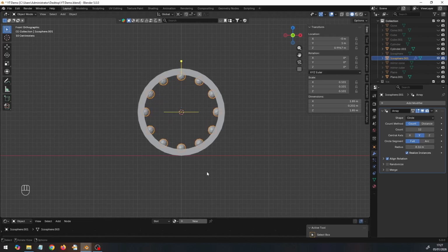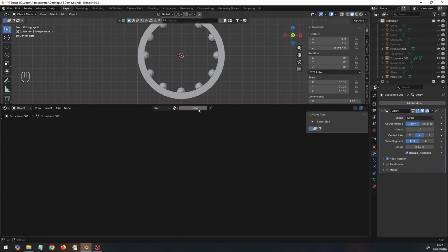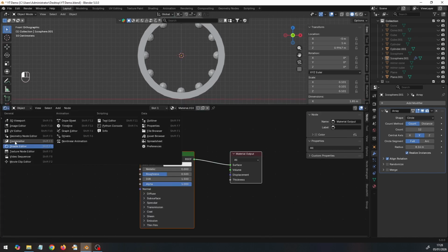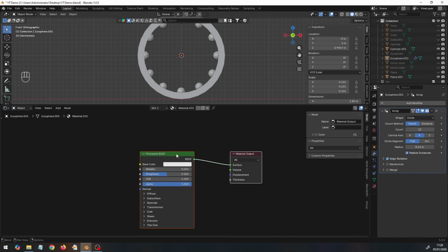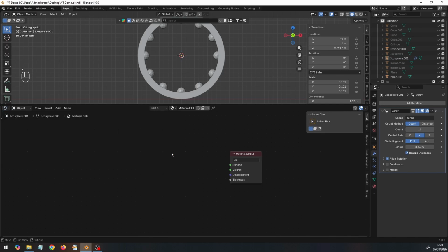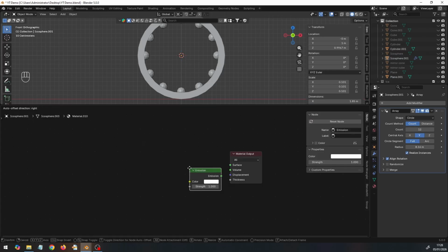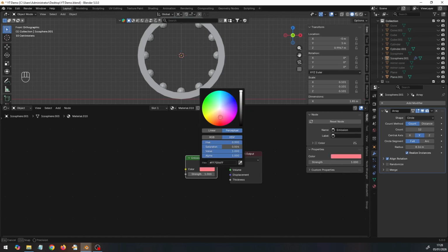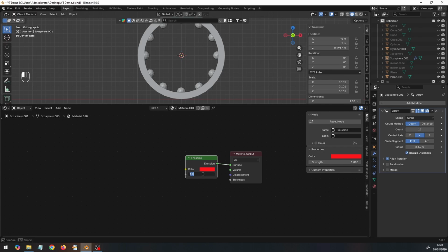the sidewall. What we need to do now is go to New, on the materials, I've got the shader open, New, Principled BSDF, X, get rid of it, A, search, we've got the emission, so we'll have the emission, we'll plug that in, we'll go for a somewhat reddish colour today, and we'll give that a strength of 10.